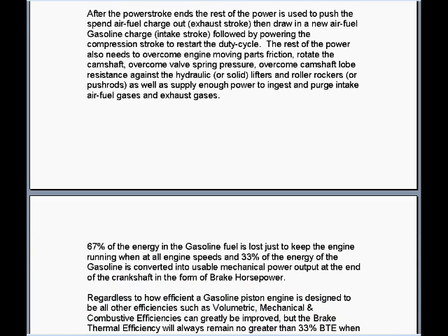After the power stroke ends, the rest of the power is used to push the spent air-fuel charge out through the exhaust stroke, then draw in new air-fuel gasoline charge, the intake stroke, followed by powering the compression stroke to restart the duty cycle.